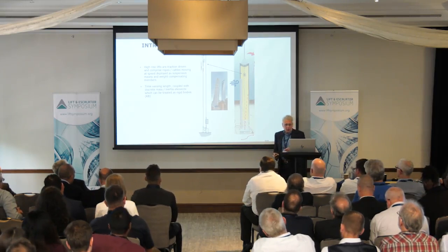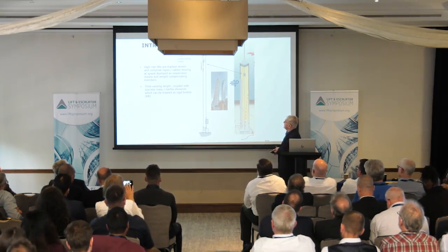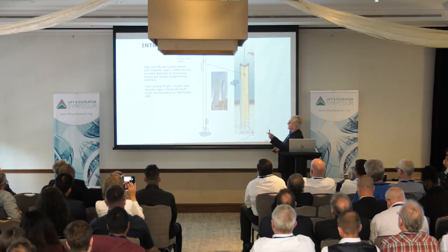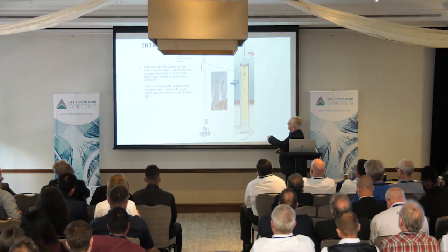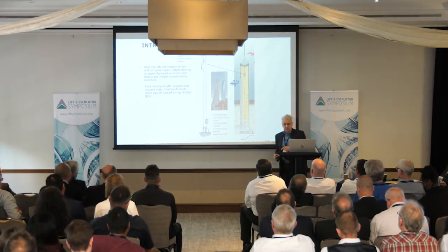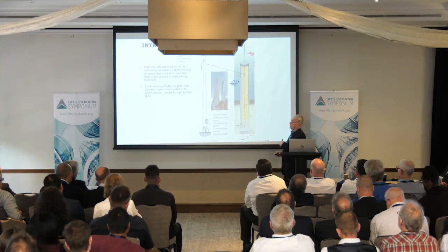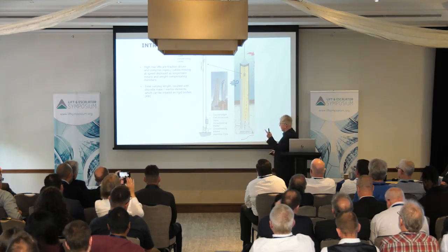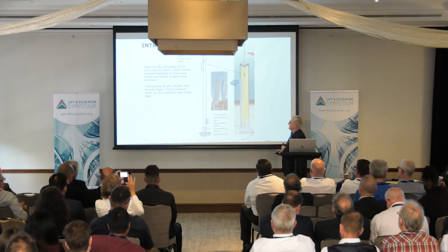The lengths of the cable ropes vary with time. We have the car suspension at the top at the moment. The car is at the top, the counterweight is at the bottom, and we've got compensating cables at both sides, and obviously hoist ropes on both sides. And also we have a compensating sheave assembly.